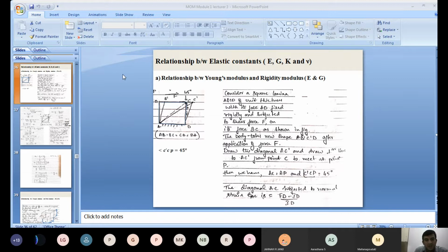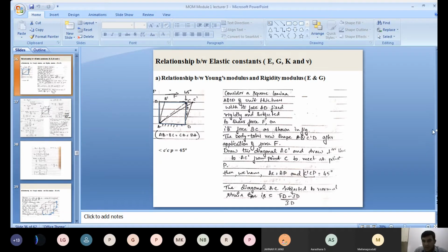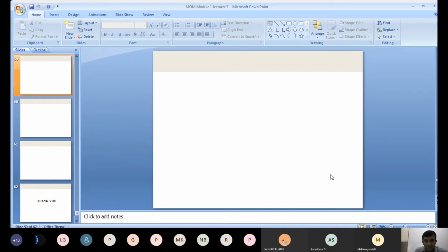Now tan gamma is equal to opposite by adjacent, C dash divided by CD. Now C dash is nothing but what? It is not deformation, it is a displacement recorded, a change in position here. That we represent as delta. Now CD is nothing but H. For a smaller angle, tan gamma becomes gamma. Then gamma is equal to C dash divided by CD. C dash is nothing but delta. CD is nothing but H. That is the formula you can see for shear strain.